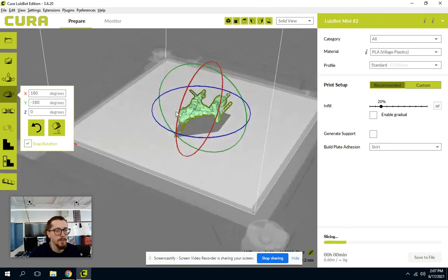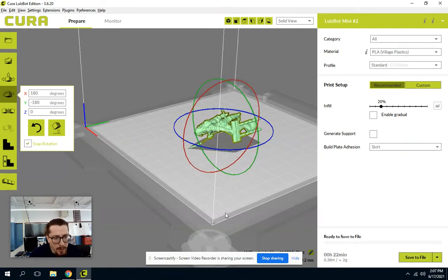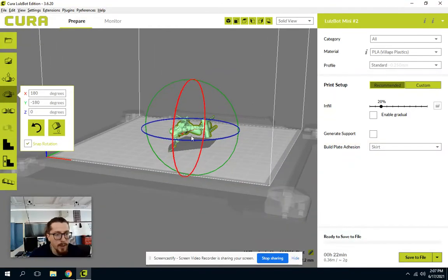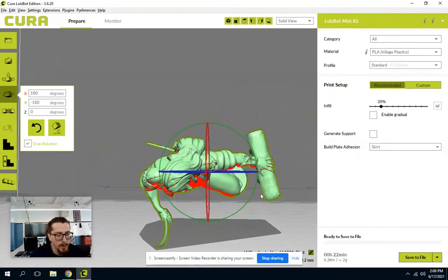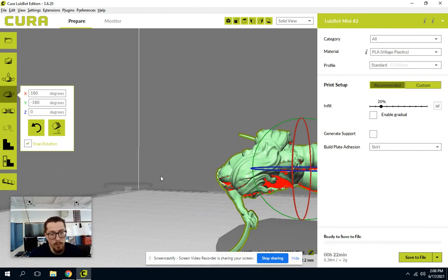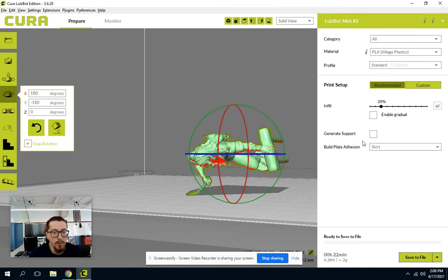And we're almost ready to print. The thing we have to worry about, though, is that if this prints right now, there's a bunch of overhang. Overhang is when you have a piece up here and nothing below it all the way down to the build plate. So that overhang, it won't print well, it won't print at all if you don't have support material underneath. So we're going to pretty much always have support on our designs if we have overhangs. There's some qualification to that, but as a rule, if you have an overhang, you want support.